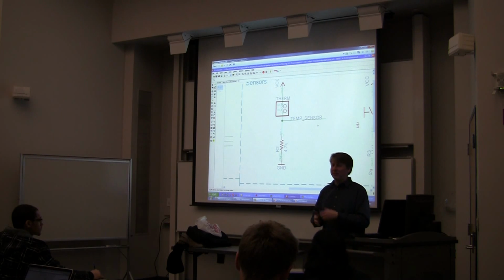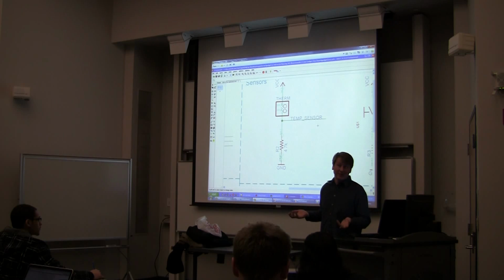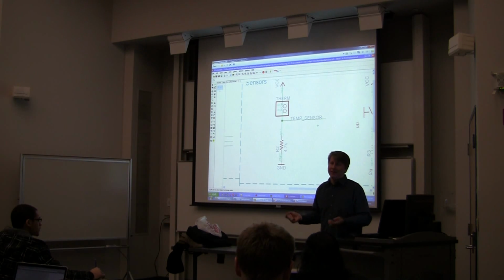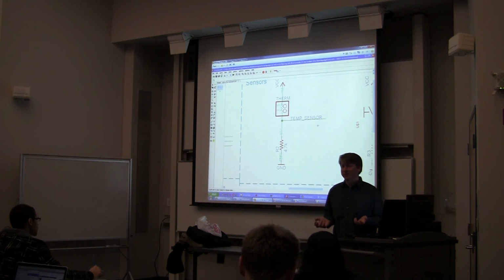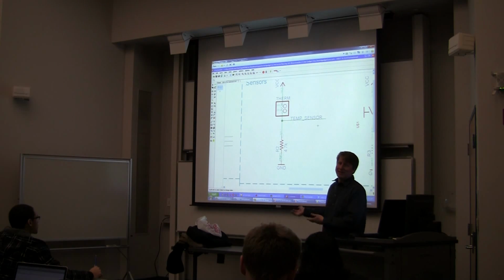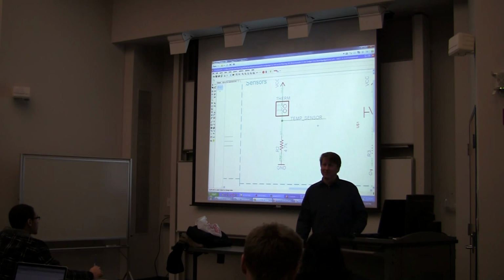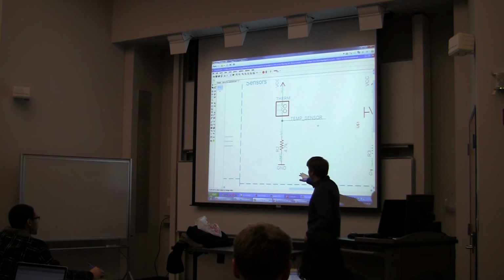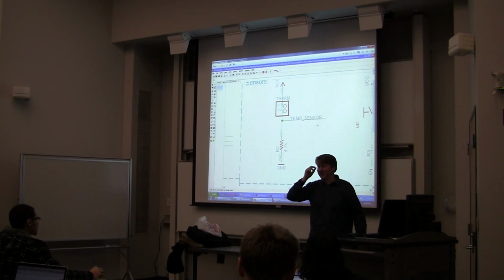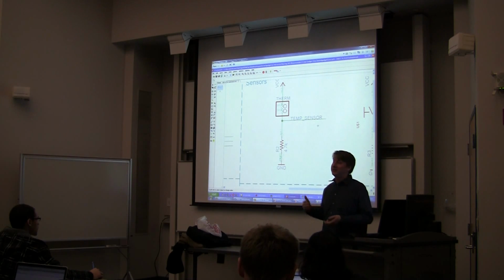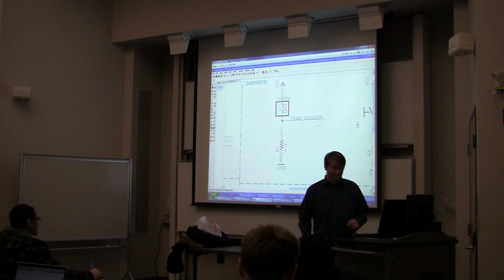And if you're doing something where there's just a too hot temperature and a too cold temperature, you can calibrate those experimentally and say, well, it's too hot when the thermistor reads 82, and it's too cold when it reads 200. So there's my values. I don't care what the resistance was. I don't care what the absolute temperature was. I just experimentally used my gadget to determine the value. So you can stress about whether this is the right value for you, or you can just use it and not worry about it. And at worst, you remove the resistor and put a different one.